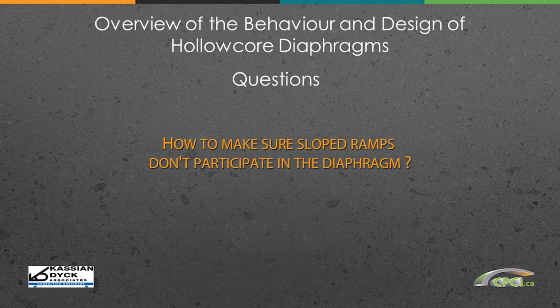So I guess that would be related to a parking garage maybe, where you have a whole bay on a slope. And if it's a sloped floor, then just like the diagonal braces I showed, it is going to become part of the system. If it's on a diagonal, it's going to potentially attract some lateral load, as a tension or compression member, compared to maybe your shear walls or other members of the lateral load resisting system.